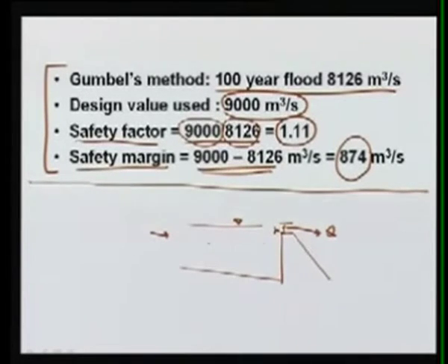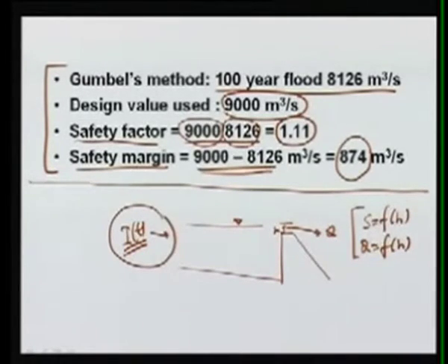The storage within the reservoir will also depend on the height h, and I as a function of time, which is the inflow hydrograph, will be given to us. So given this inflow hydrograph, we want to estimate how this water level will change in such a way that storage and outflow account for whatever inflow is coming.